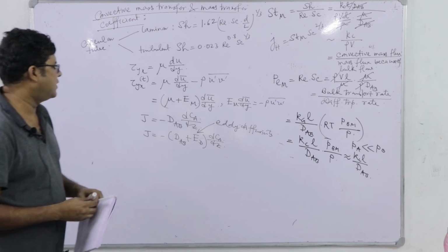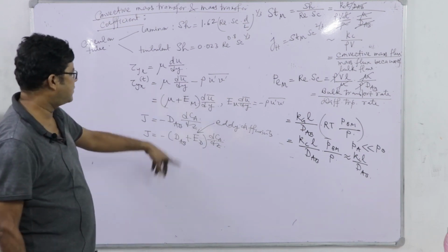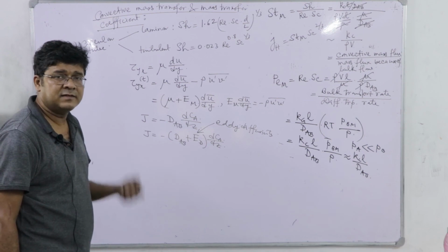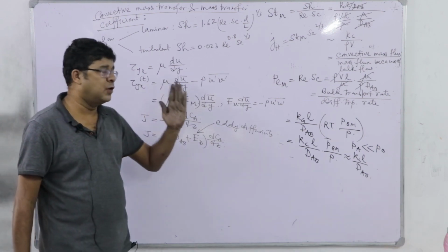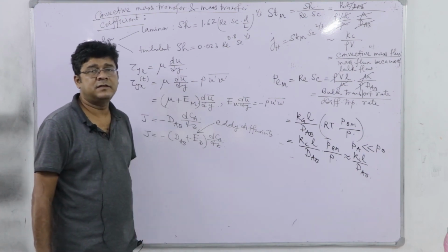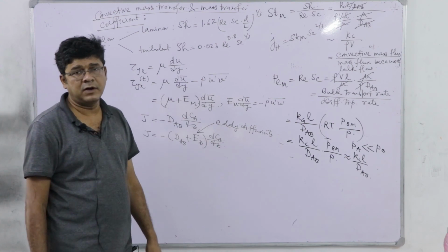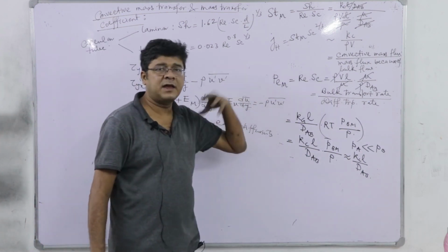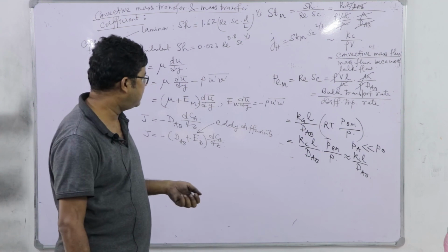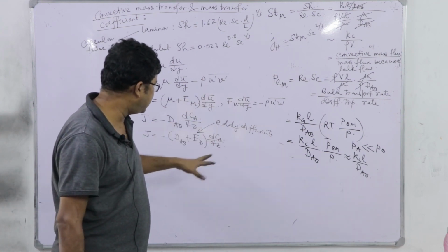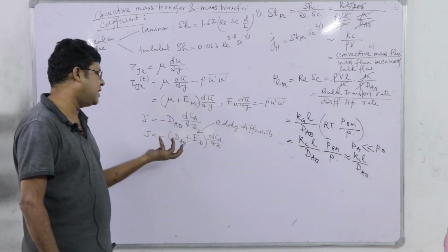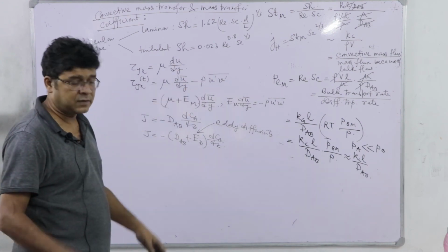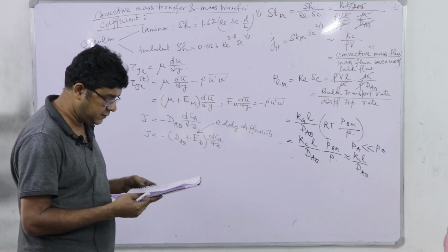Similar to eddy viscosity, eddy diffusivity is not only a property of the fluid, it depends on the flow. Eddy viscosity close to the interface is actually zero, because close to the interface we have a very low degree of turbulence. As the turbulence intensity drops, the eddy viscosity also drops, because u prime v prime average is an indicator of turbulence strength. So, Ed decreases close to the interface, and in general this is a correlation where we forcibly fit Fick's law, just like we forcibly fit Newton's law of viscosity. That is the idea of turbulent eddy diffusivity.